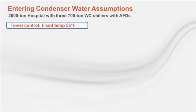The final comparison I'll make will concentrate on the effect of tower control and climate on MyPLV. The example here will look at a 2,000-ton peak load hospital with 3 700-ton centrifugal chillers, all 3 with drives. The first graph we'll look at has the tower control set to fix 55 tower leaving. This means we're always trying to maintain the tower leaving to 55 degrees. If we can't achieve the 55, we'll run the tower all out and use the corresponding leaving temp.